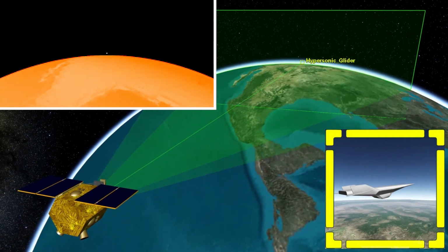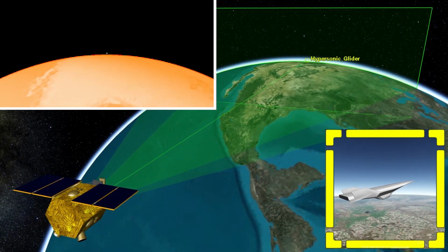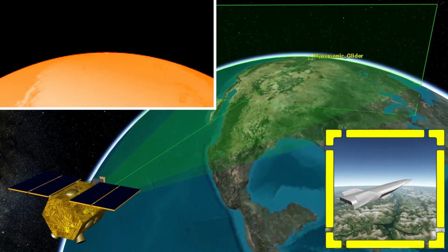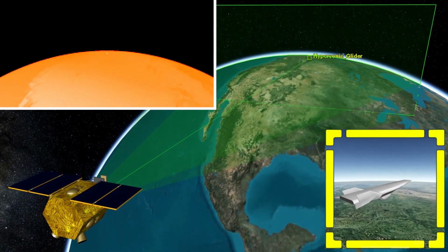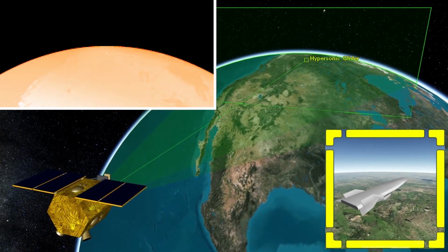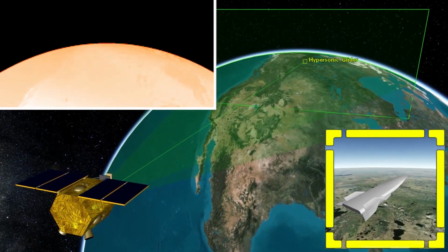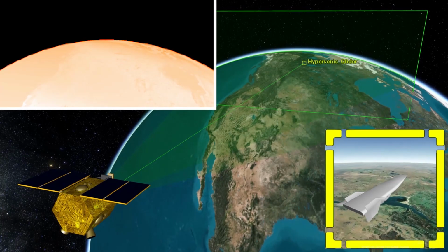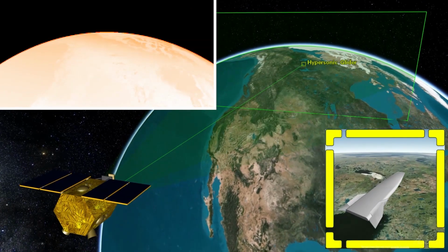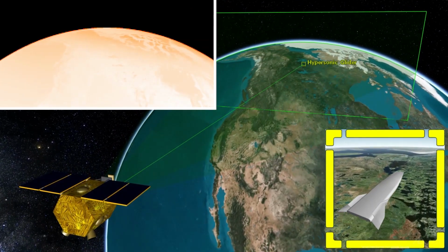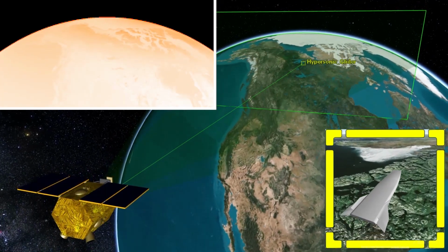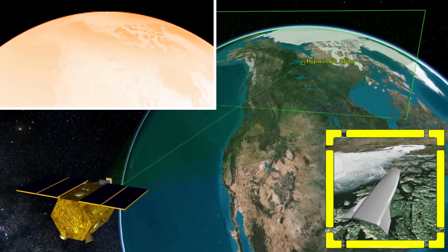In the bottom right-hand side, that's the local geometry of this hypersonic glider. And that's important because what we can see here is because we're flying in this highly elliptical low Earth orbit, we have a grazing angle where we have a perfect view of the underneath of this aircraft, those hot surfaces underneath this hypersonic. But as we fly along and we get more overhead, you see it just disappears. It disappears into the background because we're only seeing the cool surface of this particular aircraft. And all of a sudden we can now see this is no longer a radiometry problem. I'm learning the phenomenology of this, and all of a sudden it's more of a geometry problem. I realize the critical points to doing these detections isn't necessarily getting the best access times, it's getting the best access angles.